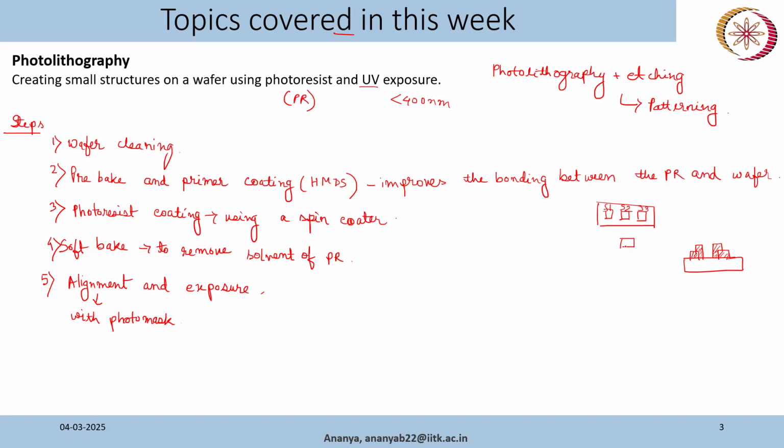Now on this piece of wafer you want to have this as one design for sensor design, and then you will go for another wafer for the second design, and for another wafer for the third design. So in that case also you may need alignment, because you want your design to be exactly on top of this. If you just look using only your eye, then your alignment may not be proper. Instead of having your design on the whole wafer, you might end up getting a design only here, say. So that is why alignment is critical.